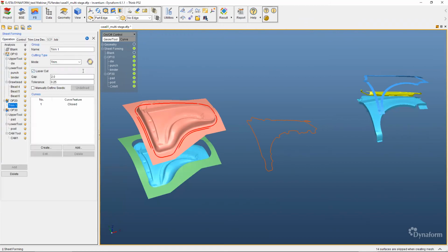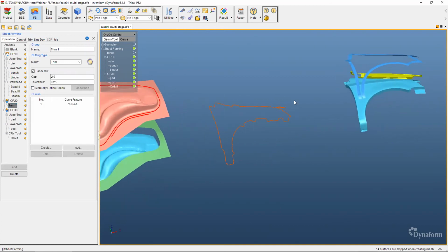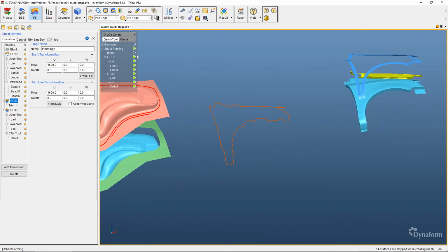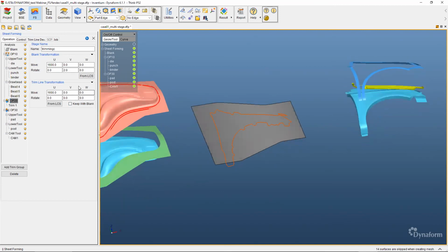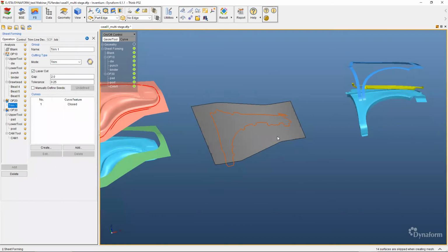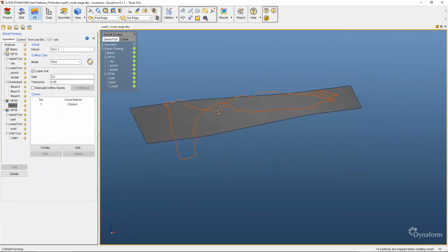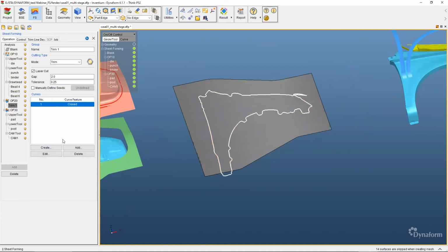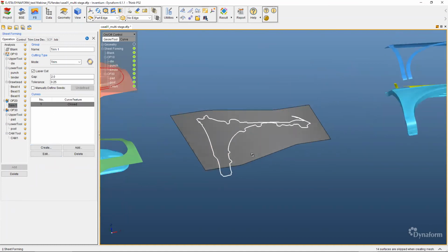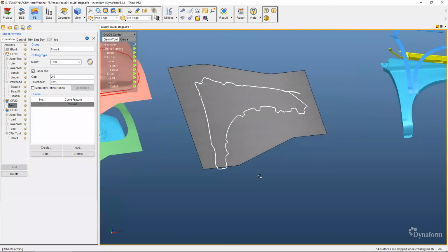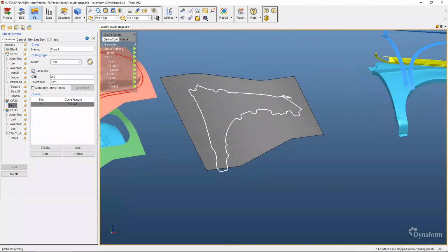So in this setup here, we have 3D trim lines. In the actual stamping process, this will be separated into several steps, but we are just saving time for running the simulations. So we use 3D trim lines instead of running trimming at different stages. If we are going to use a 3D trim line, we cannot perform a direct trim because it's in 3D geometry. That's why we have to set up laser cut options that will allow us to trim according to the normal of the elements.